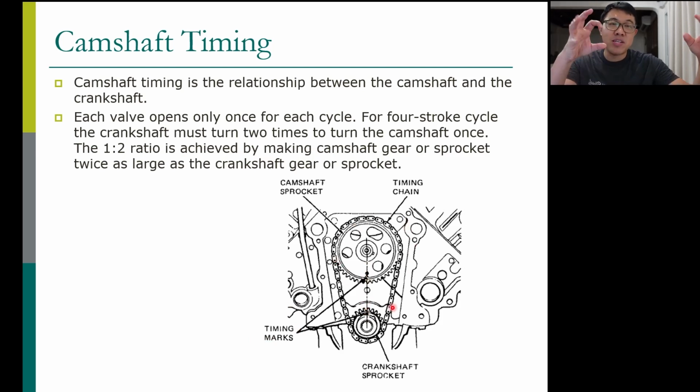So when you install it, you can turn the camshaft and crankshaft freely, right? Before you put the timing chain in. Now, before that, you have to rotate it such that you align the timing marks, before you install the timing chain.